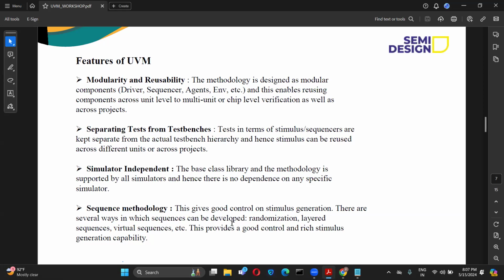You have something like the UVM factory where you register each component, so based on that you can override a particular component, like a UVM driver. You can override it, which you cannot do in SystemVerilog. This is because of the UVM methodology. Whatever features it has make it easy to change from just the top level. So these are the main benefits of using UVM.